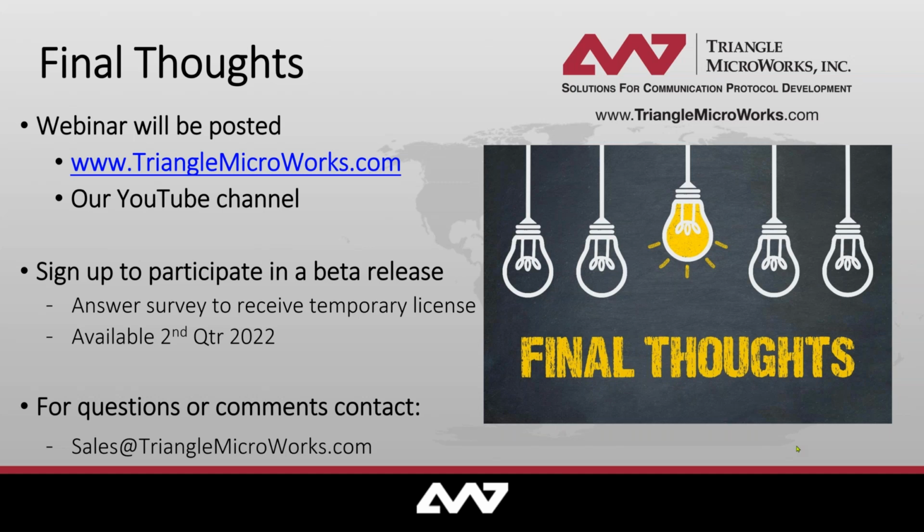Now, one of the things, and we're going to ask, I think, as a follow-up, but I'll mention it here, is on the SCADA side, we've certainly considered adding OPC support to DTM so that we can actually communicate with SCADA systems. So if you wanted to test with a gateway and the actual SCADA device and then simulated outstations, we could still do closed loop testing by monitoring the SCADA using, most SCADA systems will support OPC or something like that, and we could actually use that to monitor what's going on.